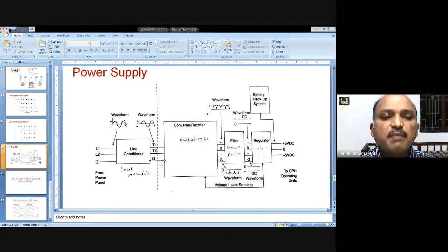So it is variable AC. We have AC with a constant. This AC is called ripples. We want to overcome this AC. How can you overcome it? You can overcome it with some filters. You can use a capacitor so that the AC available in this is removed, so only DC is allowed. So with the rectifier, we can convert alternating AC into pulsating DC.